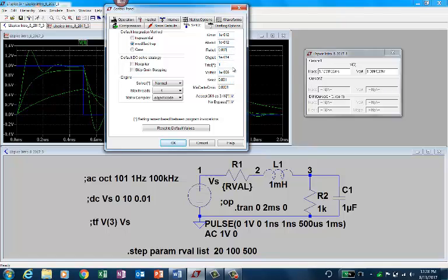Generally, if you are looking at microvolt range accuracy while dealing with 100 volts, 1000 volts, or 10,000 volts, SPICE will never find an operating point. That will give an error. So depending on whether you are looking at a circuit at 1000 volts, you have to reduce that accuracy. You cannot have microvolts; you may have to use a level of 0.1 or 0.01 volt. These are the ones sometimes you have to adjust.